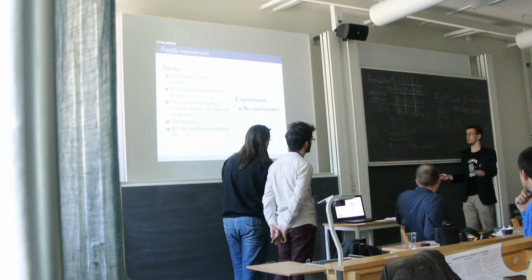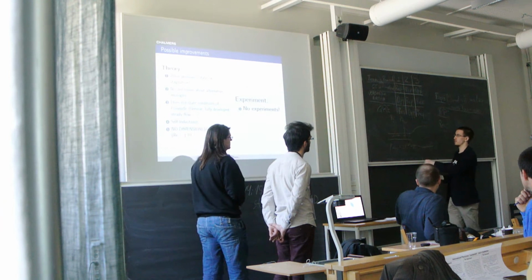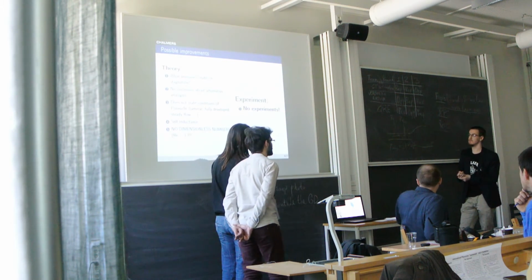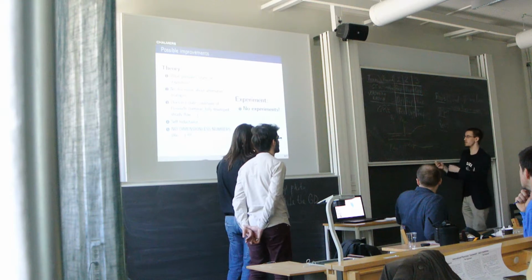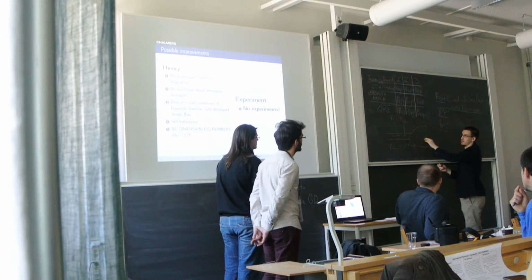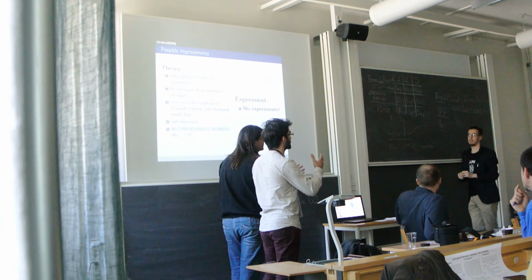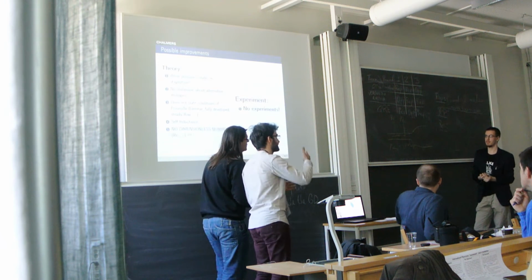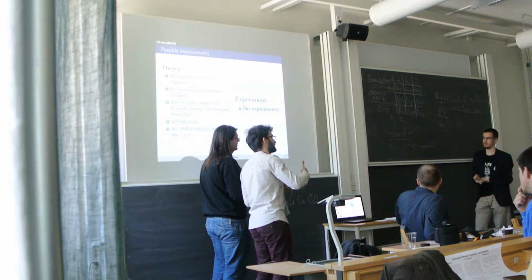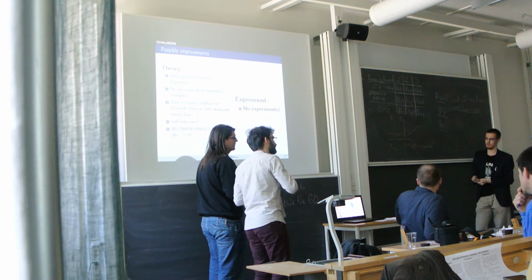But the reason I'm asking is that, okay, first of all, which one do you choose? It's the stagnation. And I think that's good, because when we move over to this pipe, then the static pressure changes. You need to check the pressure on a vertical plane on the flow.